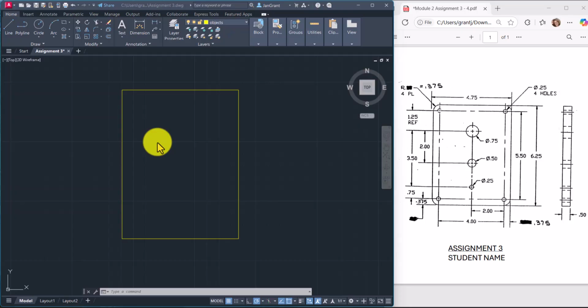let's practice that offset command. We have a lot of offsets here. We can offset for the smaller circles. We've got 0.375 here from the right side. Then we also have 2 for the center, which makes sense. And we have all of these other offsets from the bottom going up to establish those vertical dimensions of 0.375 and then 0.75 right here from the circle to the smaller circle.